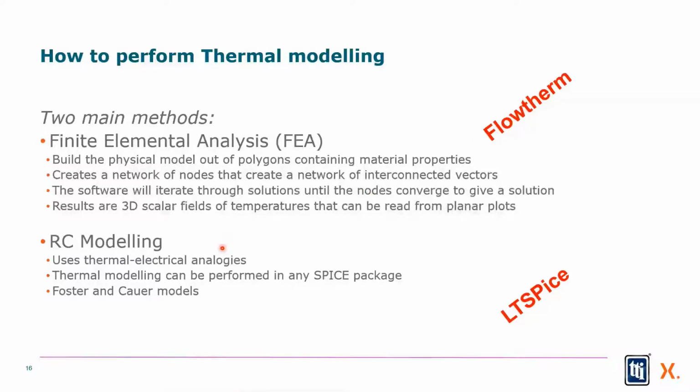So what we want to work with is something called RC, for resistor capacitor modeling, where we use something called thermal electrical analogies, and it runs under a SPICE package. I think everybody knows that you can get LTSpice for free. You can download it off the web. The variables for the Foster models or the Cauer models, which is what these RC models are called, are available free from our website. So literally for no cost, you can build a pretty good simulation in SPICE or LTSpice and determine how your system is going to operate before you solder the first part on the board.